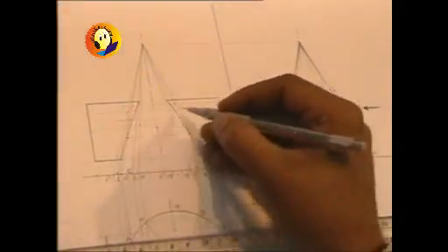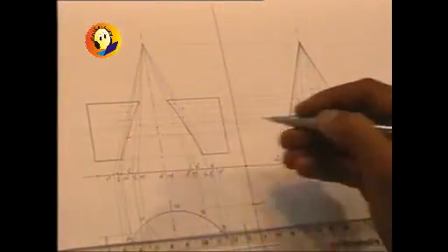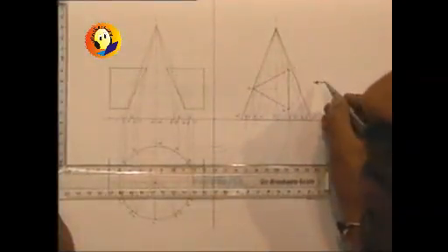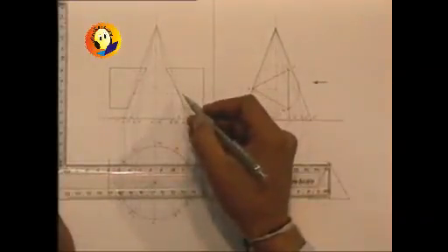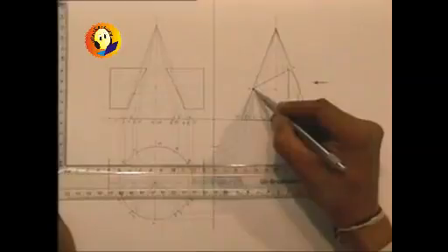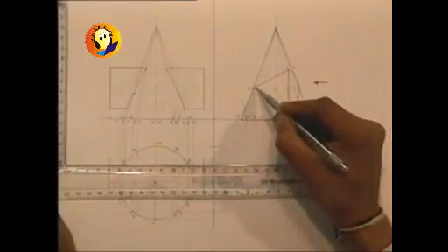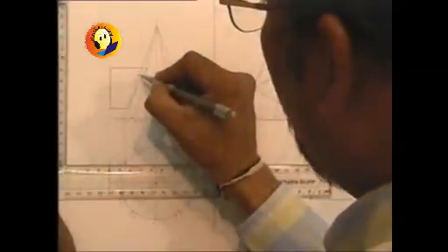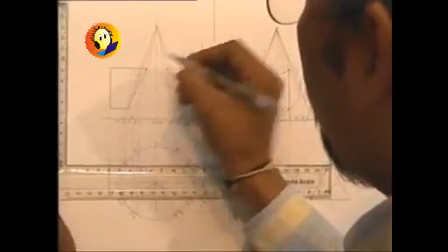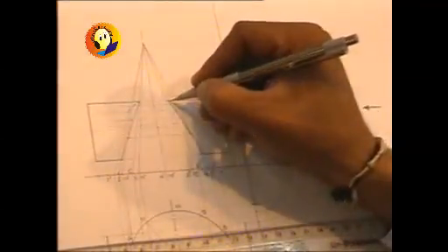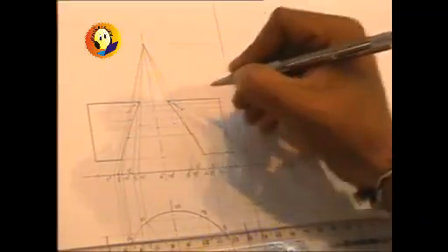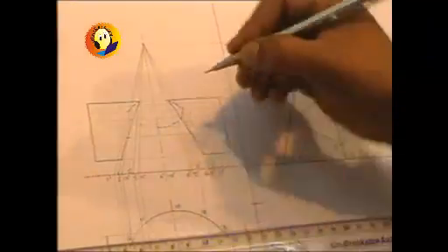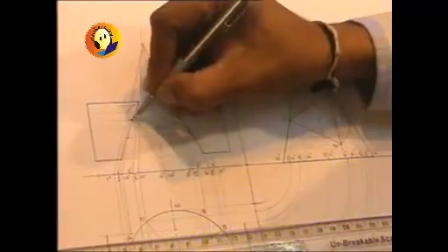So this is the shape that we get on face AC, which is behind as we are looking from this direction. As we are going to look from the right hand side direction to obtain the front view, this face will not be visible, and so we have taken the intersections of face AC. So all the points which we get over there in the front view, those should be connected by a smooth curve, but that will be a hidden curve which will not be seen. So this should be drawn as a hidden curve, which is actually on the back surface of that triangular prism.